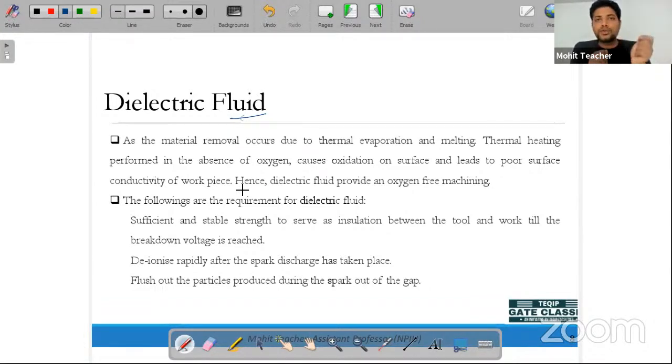Inside the electrode there is a bare wire; if the workpiece is mild steel, the wire is also mild steel. Over the bare wire the flux is mounted. Why are we using this flux? It generates shielding gases as it burns. What is the need for that?